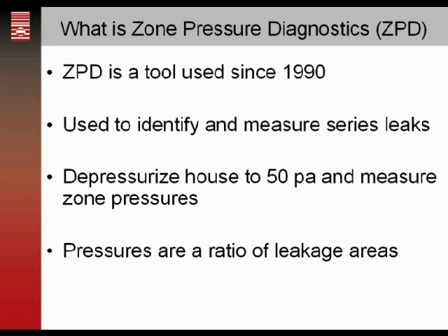And again, the leakage into and out of each of those spaces determines how much air is going to move through those. Basically, again, you need both a pressure difference and a hole in order to get air movement. So the amount of air is dependent on both of those issues.